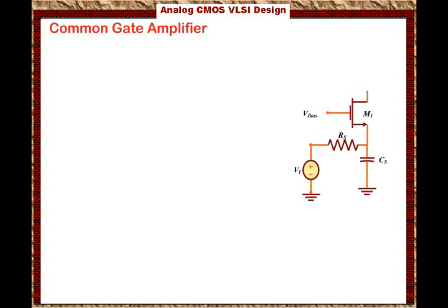to call it CS, and the output is connected at the drain, where we have VDD connected to RD connected to the drain, and there's an equivalent capacitance at the drain, we call it CD. Keep in mind that CD and CS here are the parasitic equivalent capacitances at the drain and at the source. So what we are saying is there is an equivalent capacitance that goes from the drain to ground. This is basically the parallel combination of CDB and CGD, the gate to drain capacitance and the drain to body capacitance. They behave as if they are in parallel, and they will have the equivalent capacitance.